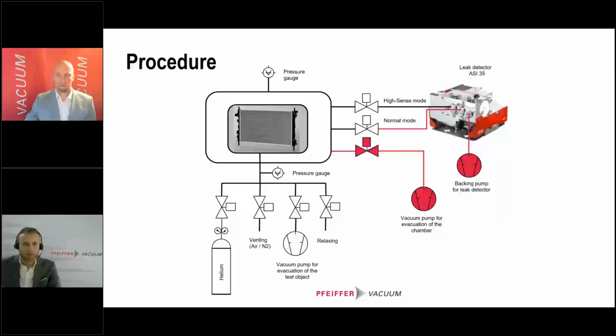Okay, so if we take a look at the procedure, we usually start with evacuating the chamber, while at the same time the leak detector is running and backed by the backing pump, valve still closed.